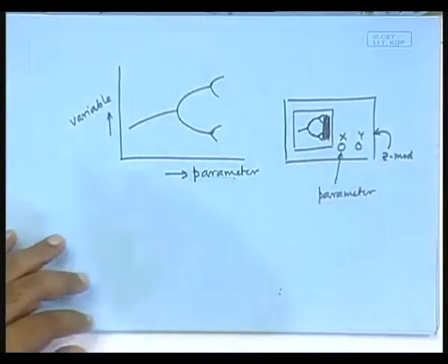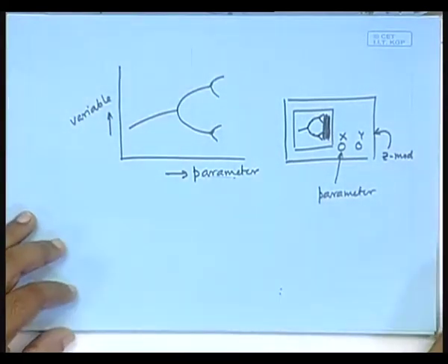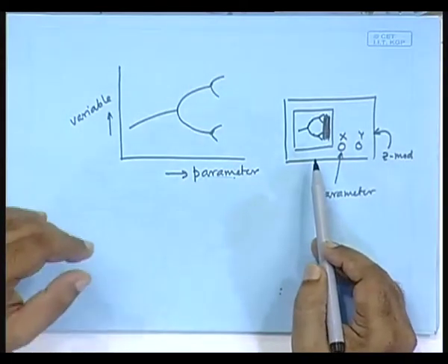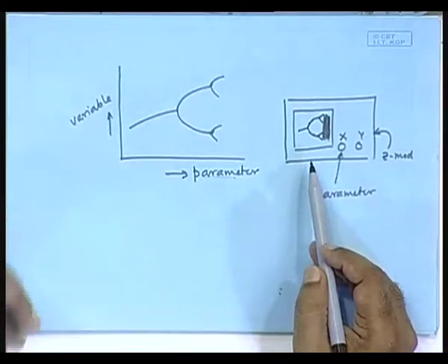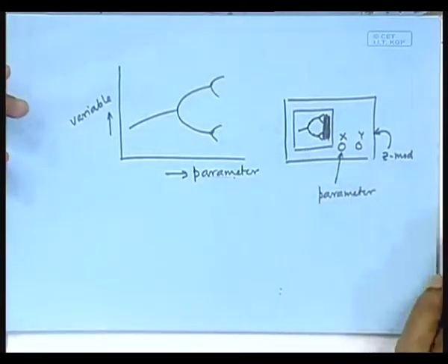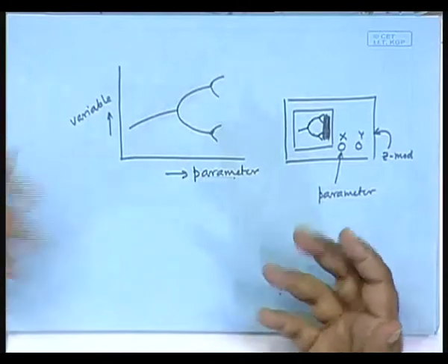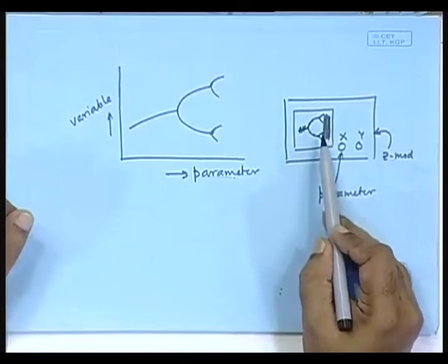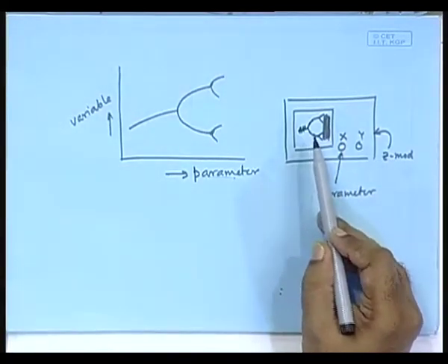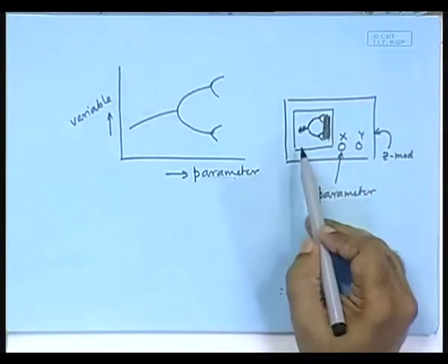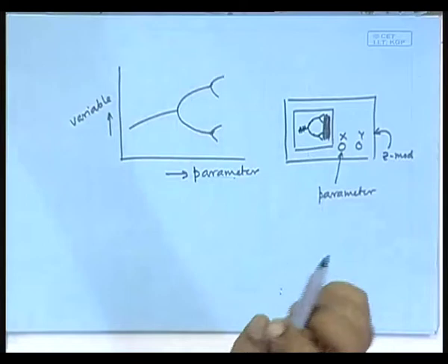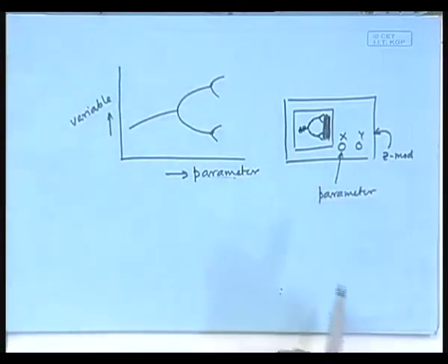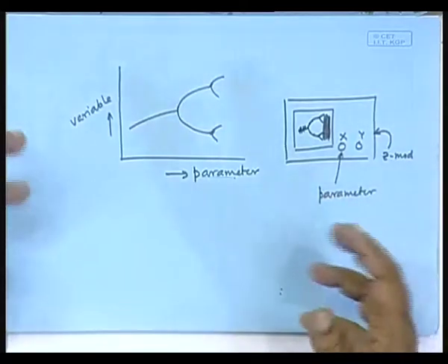Okay. This is another nice way of doing it, but one word of caution: the digital storage oscilloscopes measure the actual signal and the noise with equal intensity. So, if the system is noisy, then you will see a lot of smudge around this if it is done with a digital storage oscilloscope, while in an analog oscilloscope the actual signal is brighter than the noise signal. So, you see the bifurcation diagram better with the analog oscilloscope, but nobody nowadays does it because it is somewhat cumbersome to switch lights off and put a camera and do this slowly.